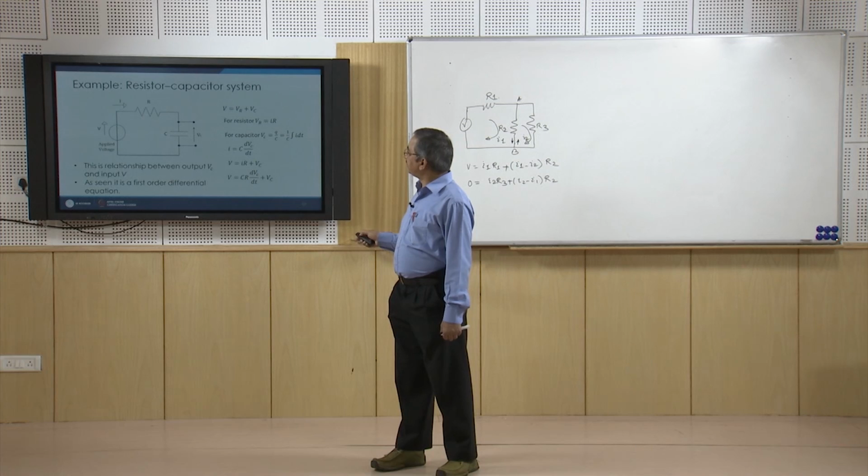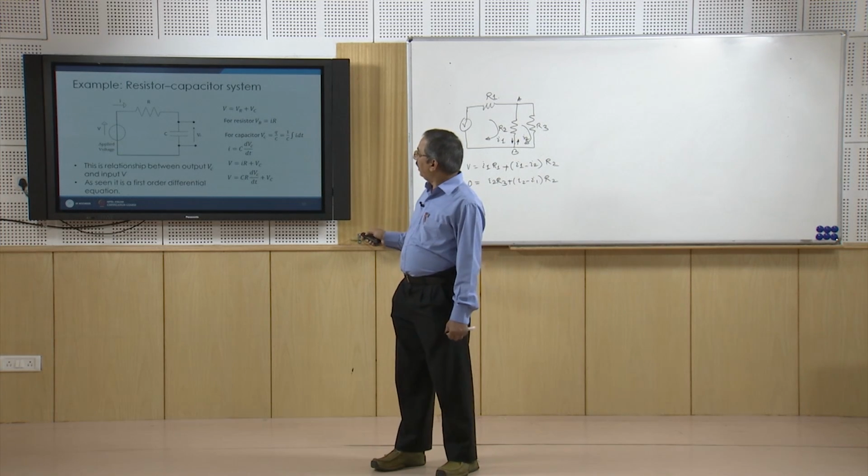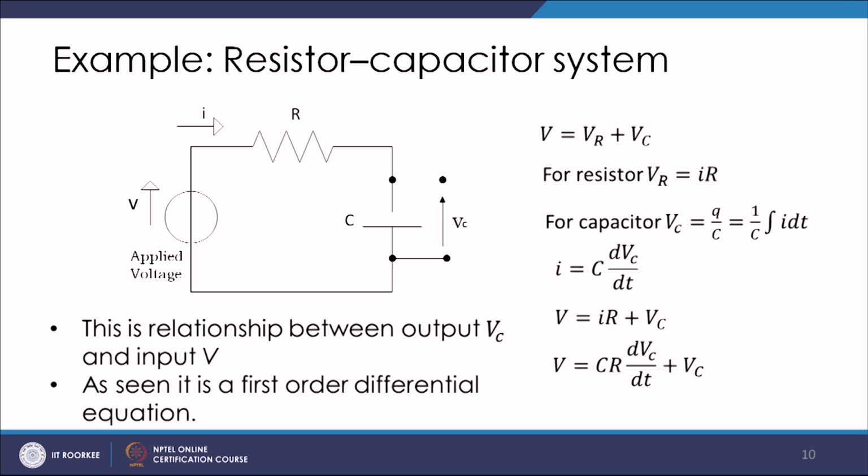By seeing the circuit as a loop here, we can apply Kirchhoff's voltage law, or Kirchhoff's second law. So, here V, the source voltage, is equal to the voltage across the resistor plus the voltage across the capacitor. So, V is equal to VR plus Vc using Kirchhoff's voltage law. Now, VR, the voltage across the resistor, we all know from Ohm's law is going to be I into R, where I is the current through the resistor and R is the resistance.